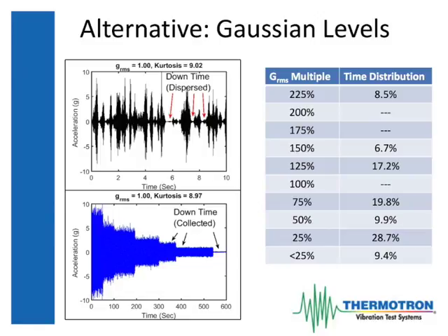There is a faster way to do it. If nothing else, you could make a level schedule out of it and just run the levels that are relevant. So maybe, in this case, 225, 150, and 125. Maybe 75. But you could save 50% of your test time just using this very crude technique. And given the kurtosis algorithms that are on the market, you can make this schedule for any kurtotic test. So it turns out using kurtosis is never, in any situation, the fast way to damage your product.